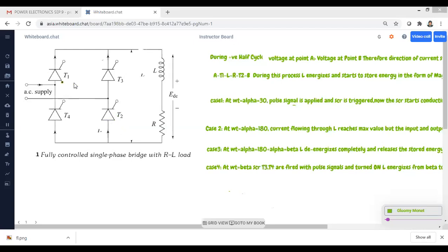If I am turning on T1 and T3, we cannot convert bidirectional current to unidirectional current. Okay. So if you are turning on T1 and T4, we cannot convert bidirectional to unidirectional. In fact, we lead into the short circuit condition. So what is the explanation? All students ready? Okay, come on.